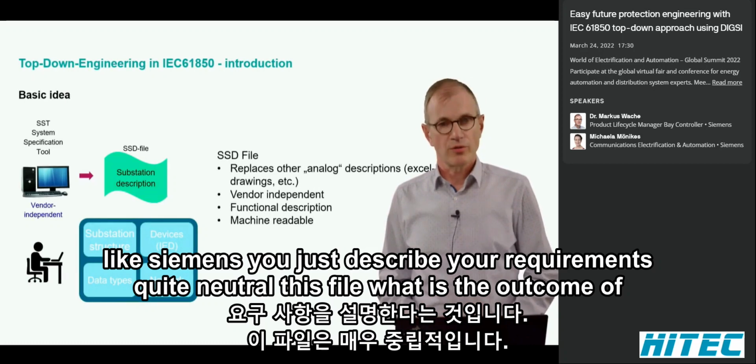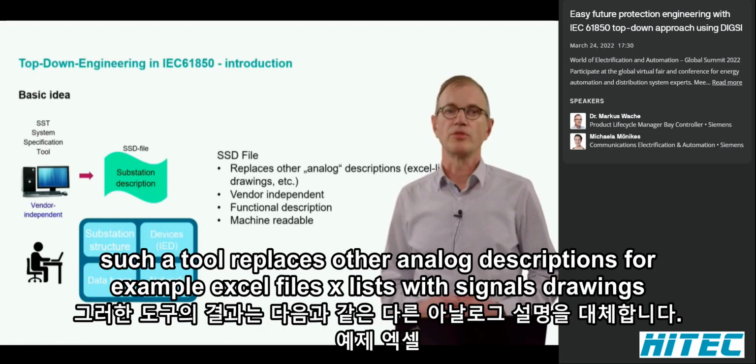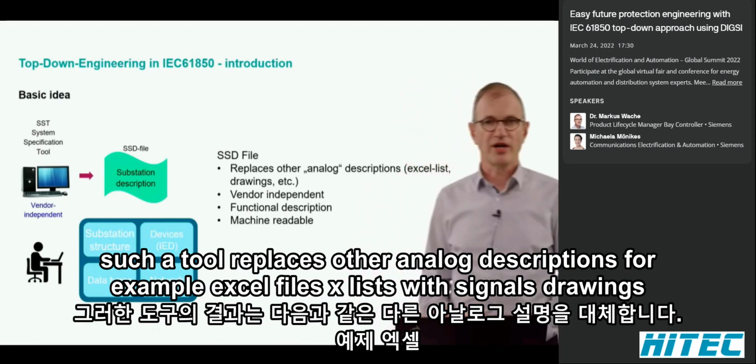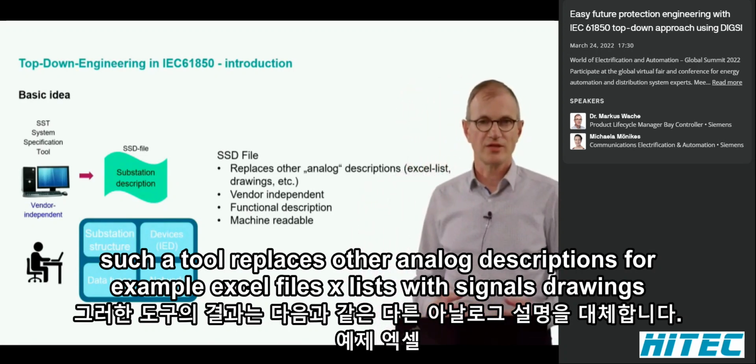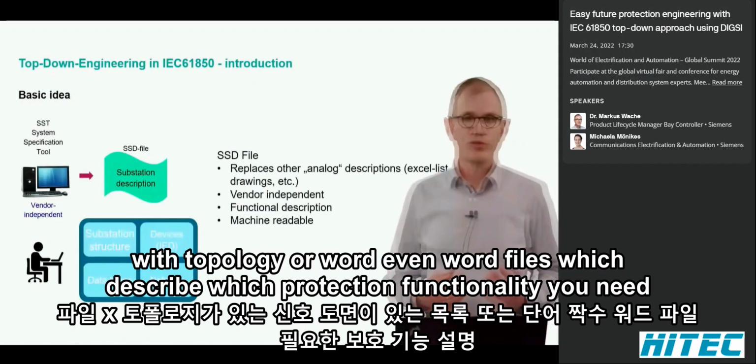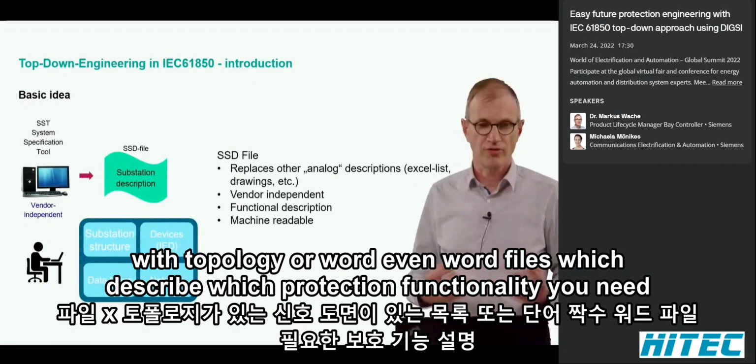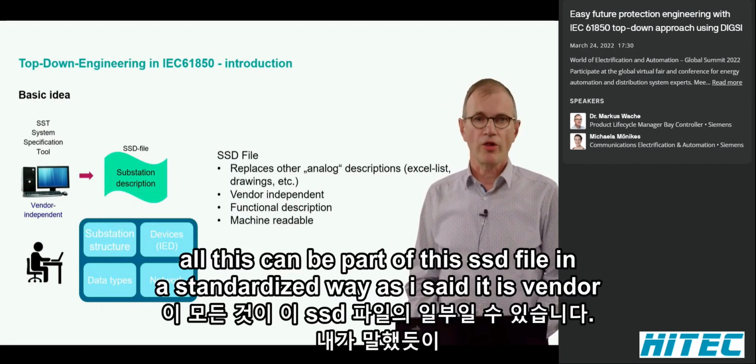The file, which is the outcome of such a tool, replaces other analog descriptions. For example, Excel lists with signals, drawings with topology, or even Word files which describe which protection functionality you need. All this can be part of this SSD file in a standardized way.